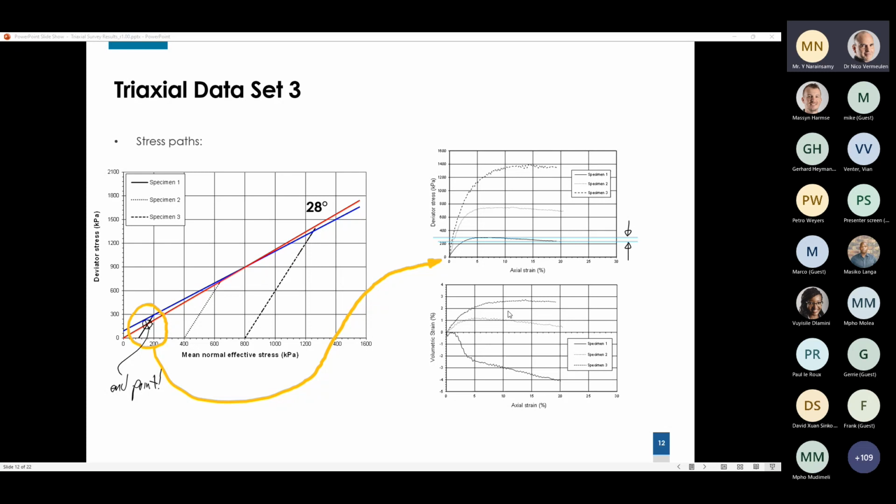Unfortunately, like I said, Andre did most of the hard work here, so I'm just presenting the outcome of the analysis. But you make a valid point, and one of the biggest struggles for me personally with triaxial test results is keeping track of the void ratio changes, up or down. Starting from the initial void ratio density that we can determine from the sample before it goes into the triaxial test, and then tracking its changes throughout the whole process of saturation, even flushing.